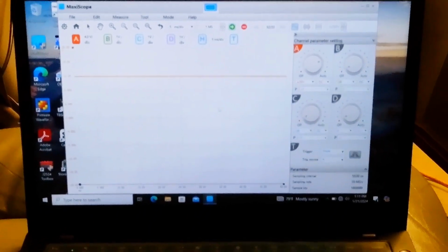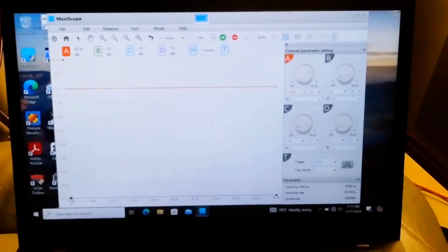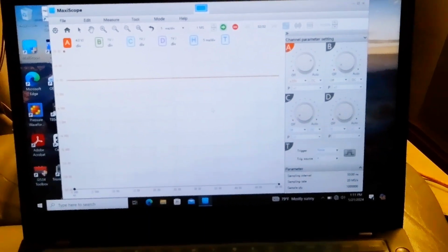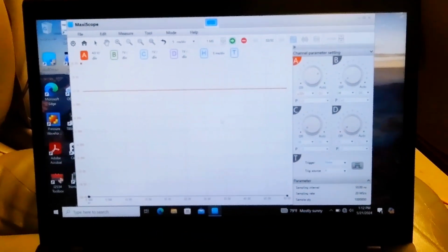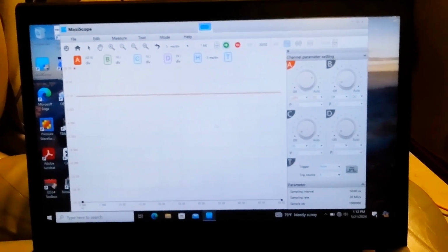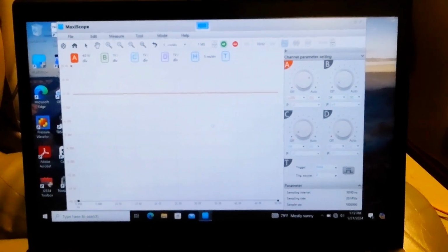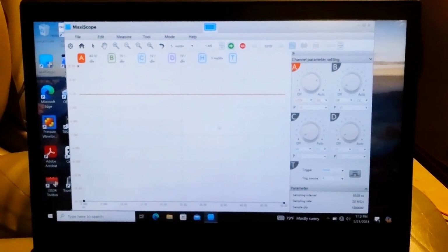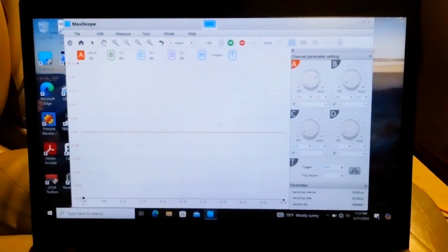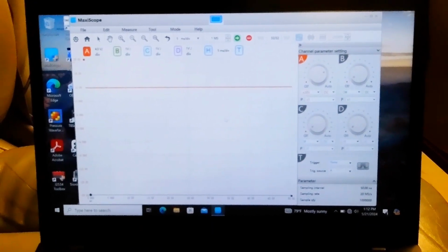All right, right now I am in pin D. Actually, yes, I am in pin D on this blower motor resistor, which should be grounded through the resistor itself to pin A. As you can see, we're at 12 volts. So we clearly have no path to ground through this blower motor module. I'm calling it a blower motor resistor, but it's actually a blower motor module. These are not resistors. So this should ground through the module and be grounded.